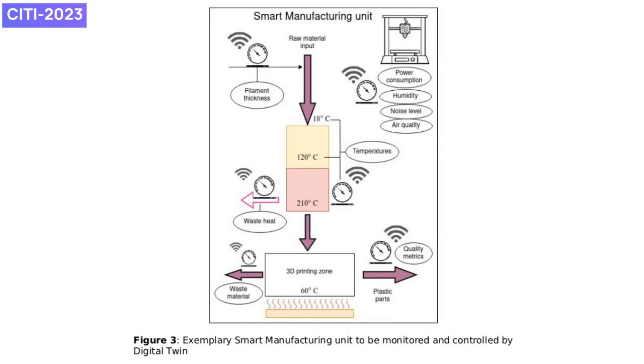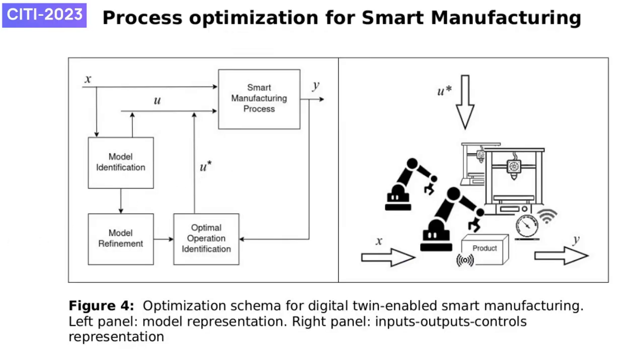In order to determine the energy-intensive processes or equipment, it is necessary to gather data on energy consumption, production and efficiency using specifically selected smart sensors, meters and other monitoring devices. Algorithms can improve the machine's performance to consume less energy by assessing data on operating parameters and the amount of material being used. Based on these data obtained from the set of embedded sensors and external data generators, a reference matrix would be developed, needed to mathematically describe each process and its dependencies.